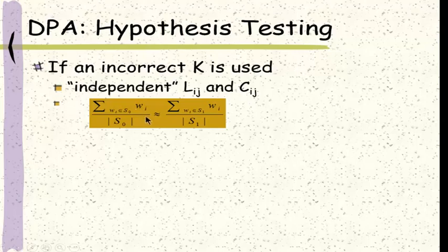In this case, because L sub i's and c sub i's are not correlated, in each of these sets, the power waveforms collected will include those where the output is 0 and those where the output is 1. So when we do the average, we will have very similar values. So their difference, which is the DPA value, will be very close to 0.